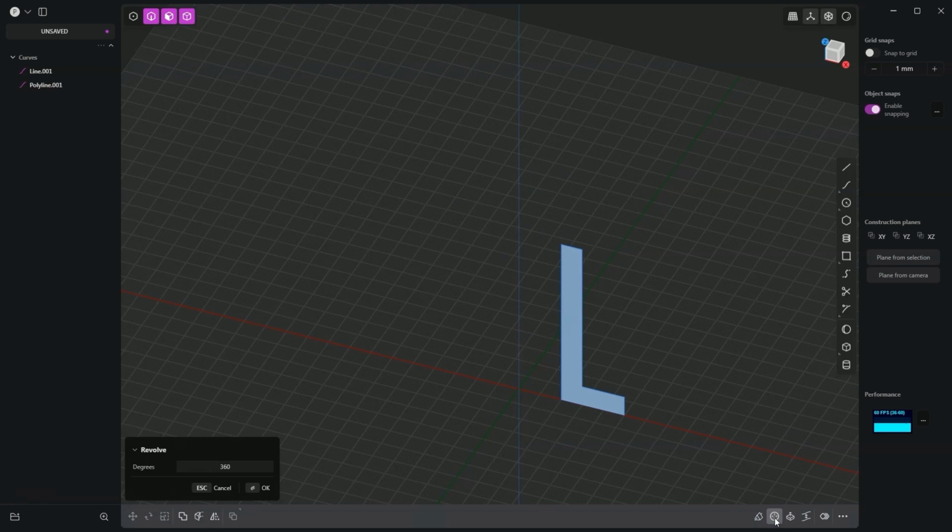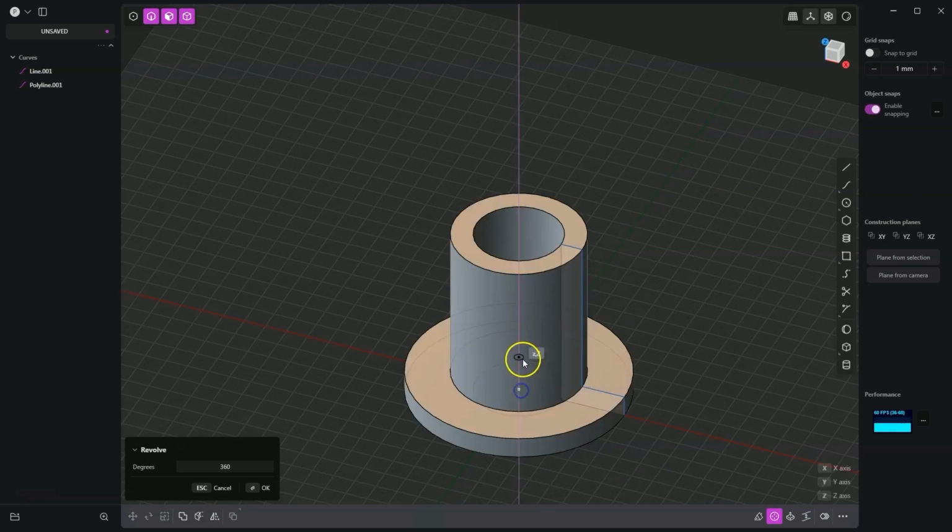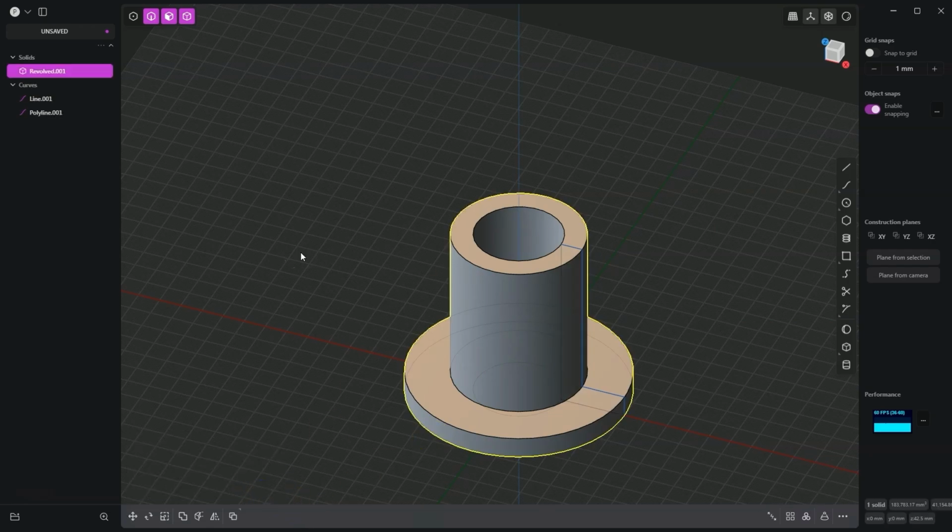We define the axis by indicating 2 points. For the first point, select the origin of the coordinate system, and for the second point, select any point lying on the z-axis. Just click the left mouse button when this snap is active. In this way, we have created this solid. Click OK, and we can proceed to create the next fragments of the geometry.